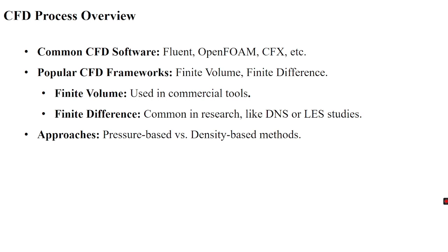There are many common software packages generally used for CFD analysis, like ANSYS Fluent and OpenFOAM. These software tools are built on different frameworks for solving the governing equations of fluid flow. Each follows a specific methodology for discretizing the computational domain, selecting the numerical scheme, and solving the equations which govern the behavior.